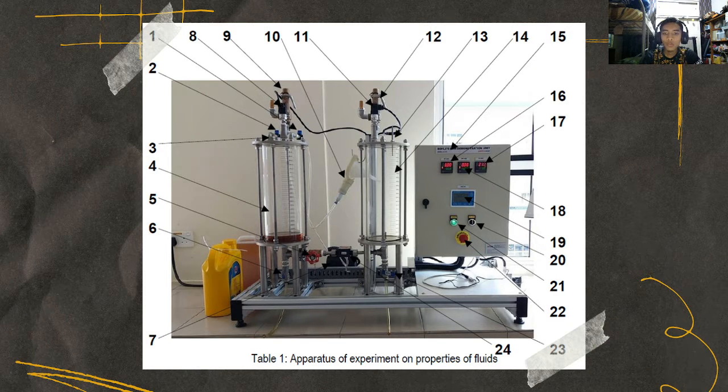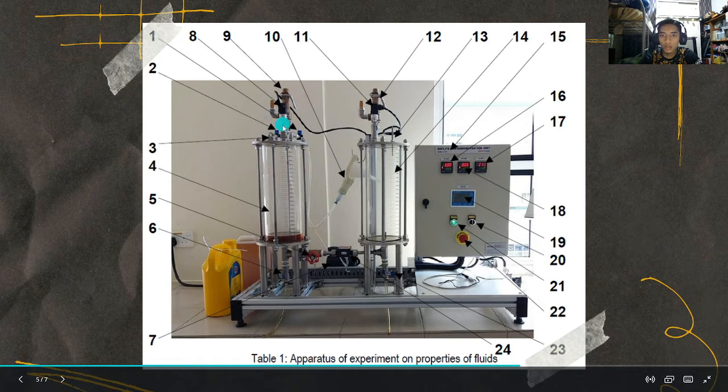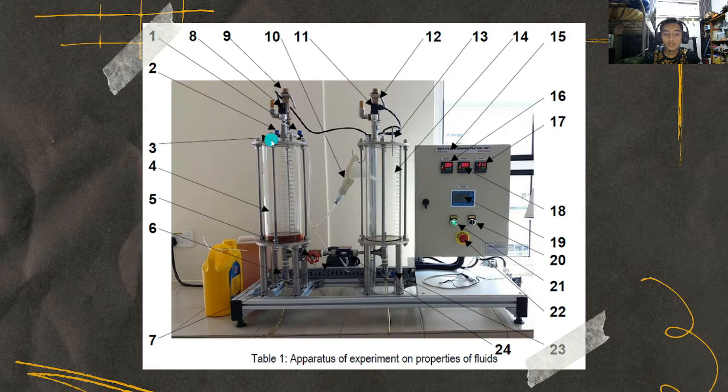The BV101 is number 2, this one, this valve. And then we record the initial pressure reading on PT101, number 16, and the volume and the temperature of air in T101. And then we will switch on the air compressor, which is number 7.